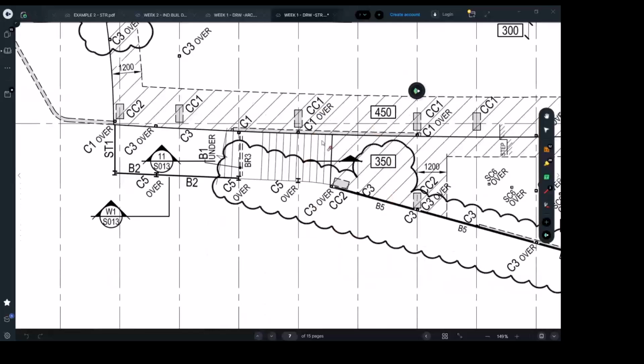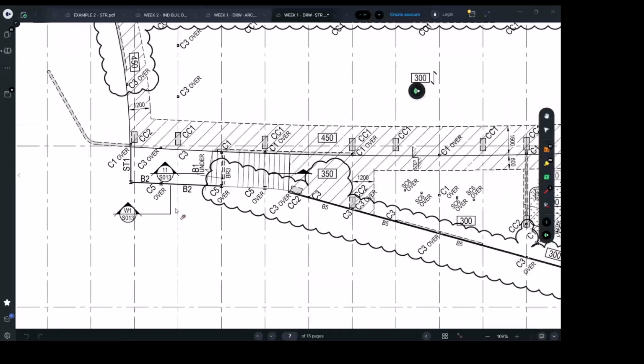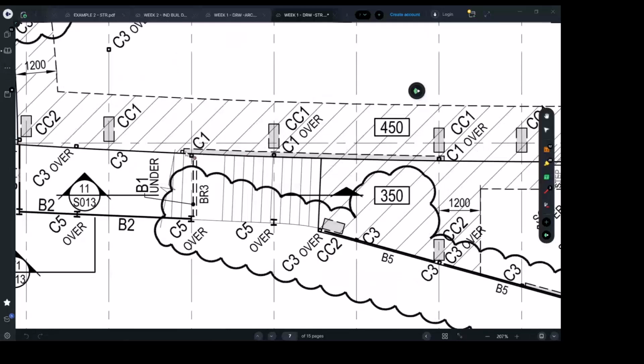So features and characteristics mean there are some detailing construction engineers need to pay attention to, otherwise they may miss the construction concept and lead to major mistakes. Like, for example, if you didn't recognize these walls are actually stabilizing, you may end up not building the walls. And I can tell you this happened a lot.